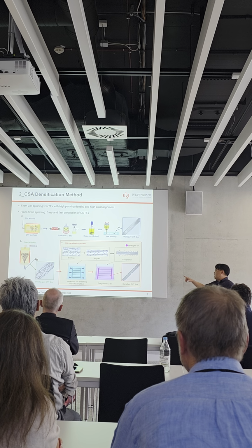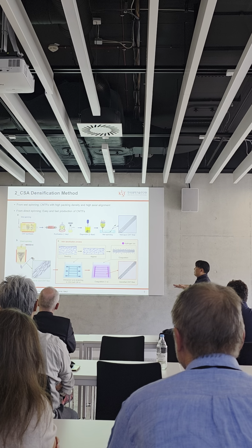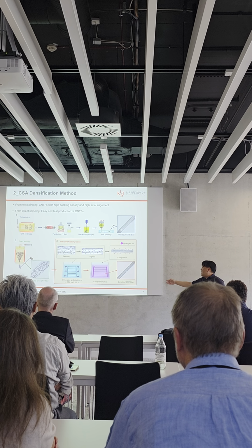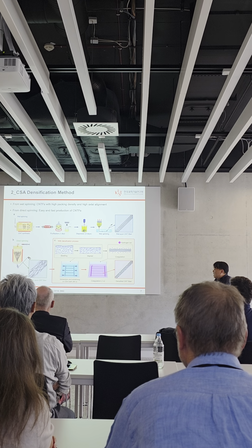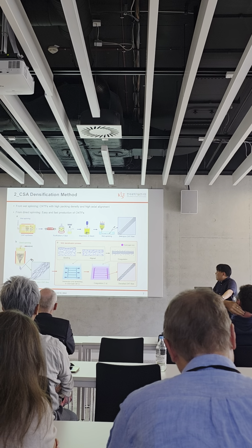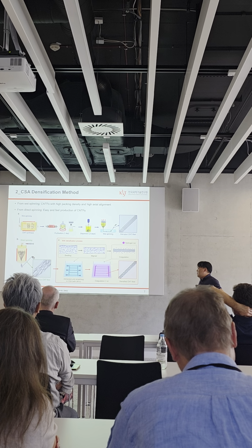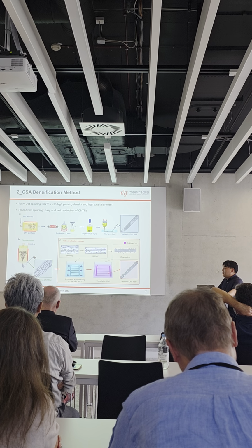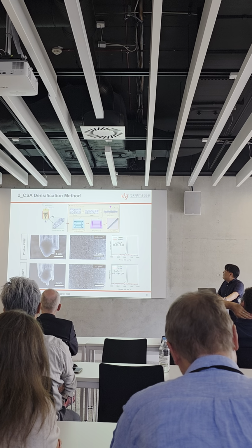So we can stretch the fiber in the CSA bath, and then move it into acetone as a coagulant, and we can make a very dense fiber with a very packed internal structure. It takes just 60 minutes for the immersion and stretching, so it's a very quick process to improve the properties of the CNT fiber.